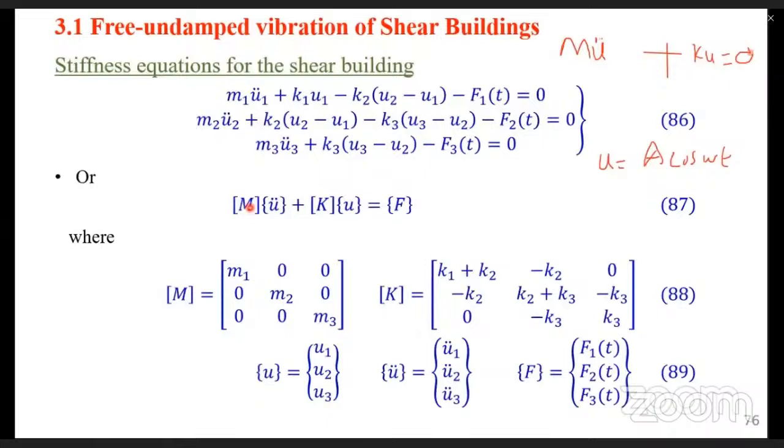So it is displacement in multiple bodies. Displacement components for different masses or bodies, M1, M2, M3, depending on the floor level. Okay, so I prefer you use the displacement instead of forces, because the description of the degree of freedom is about the displacement component.